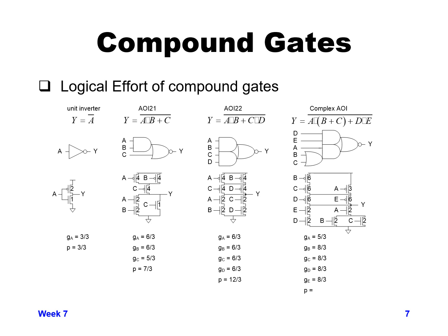Then our propagation delay will be, the output node Y is connected to two size 6 PMOSs and two size 2 NMOSs, so that gives us 16/3. So you can see each of these has a very different function to it, but it's relatively easy to come up with the logical effort and the propagation delay to go through with our examples here.